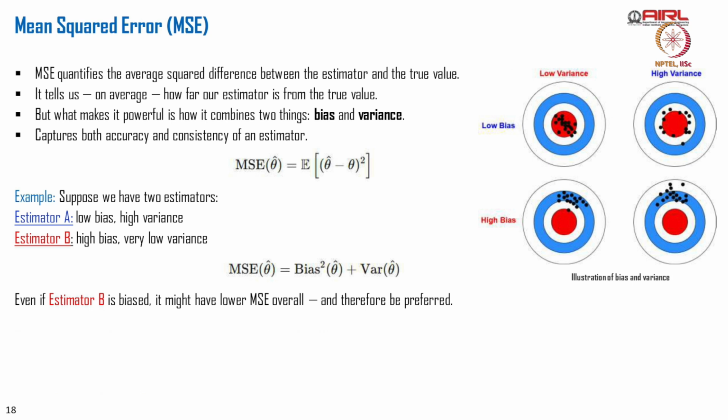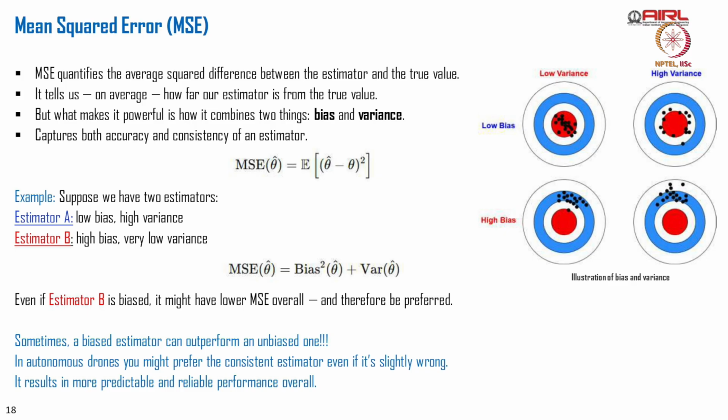But the ultimate aim is to get low bias and low variance. I do not want even the bias to be there. High variance is dangerous. Every time you measure, it says you are at a different height, so your controller will start reacting and you start consuming more energy, constantly correcting, and your mission time will come down significantly.